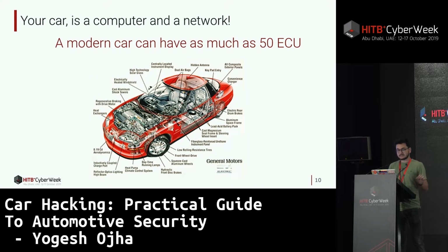Your tire pressure sensor being synchronized to the infotainment system, the internal combustion engine sharing data with the infotainment system, and all this sort of information has to communicate with each other. And for that, you need a network. As modern automobiles contain as many as 100 electronic control units, the safety of the vehicle relies on the near real-time communication between the various ECUs.